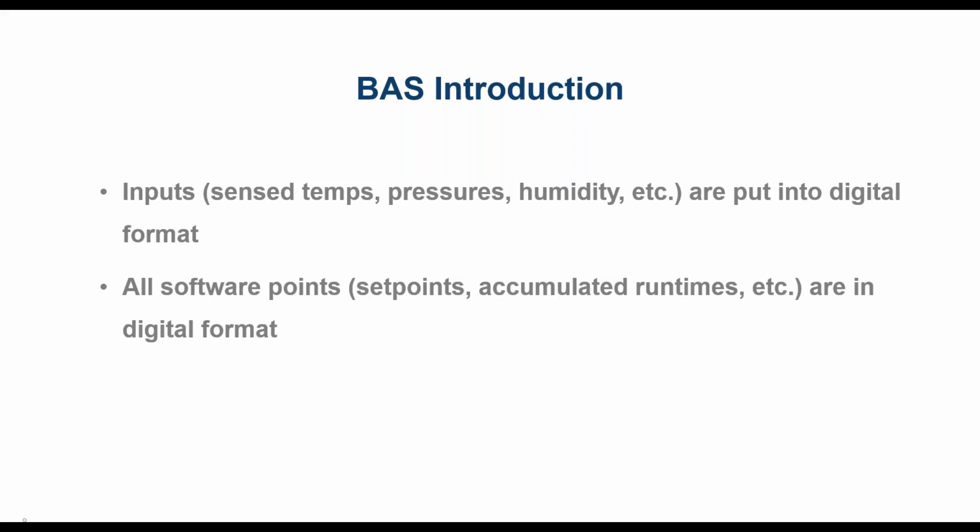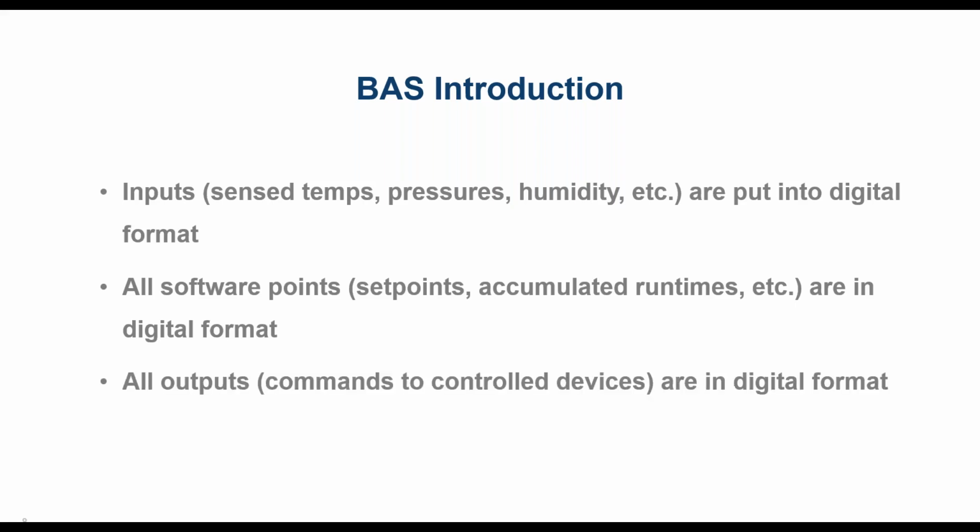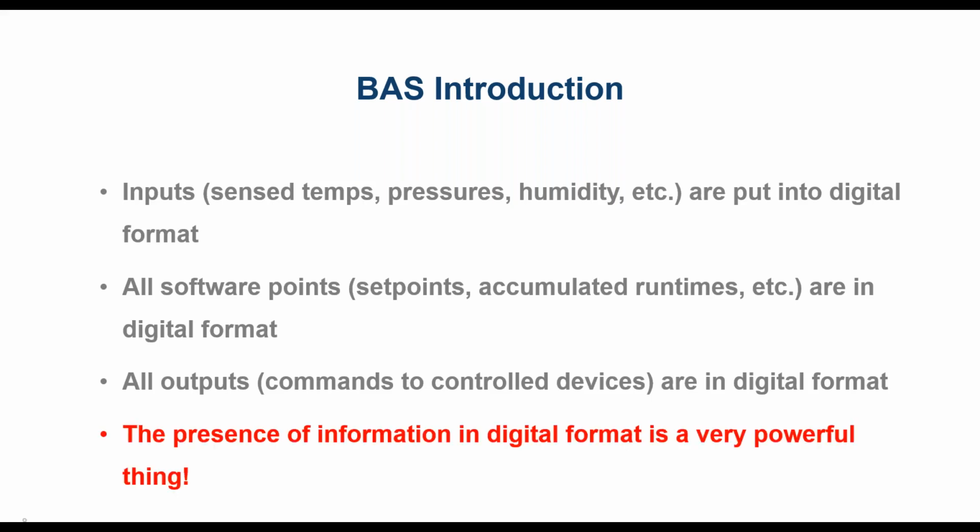Additionally, all the software points, think of the set points or the accumulated run times on equipment, things of that nature, all that information is going to be available in a digital format as well. And then all of the outputs, that's all the decisions that these controllers make that manifest themselves as commands to control devices, are also going to be in a digital format. So if you have all this information in a digital format, it's a very, very powerful thing.